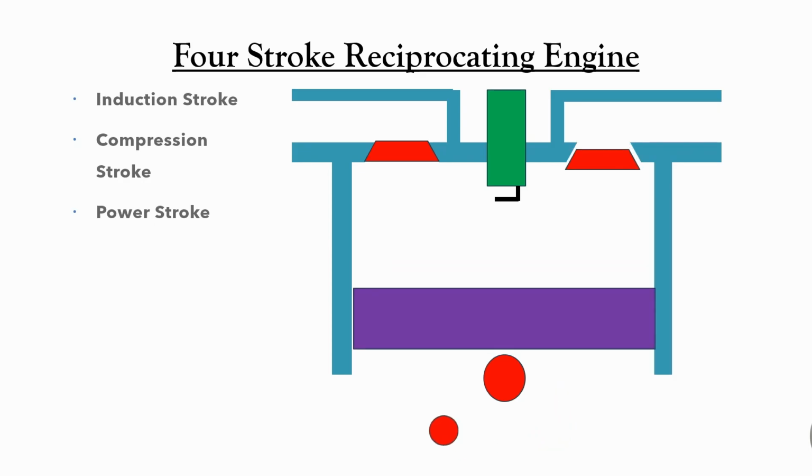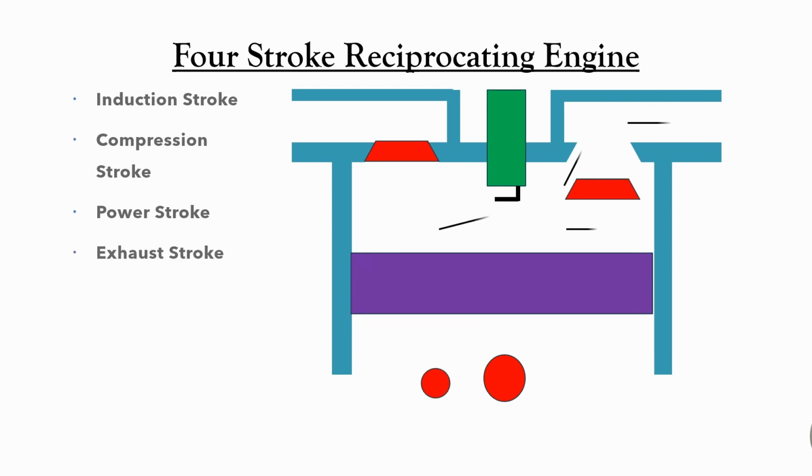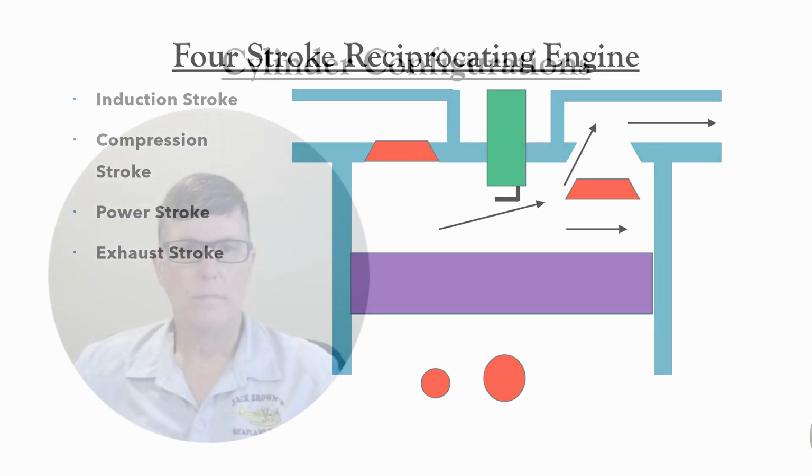During the exhaust stroke, the exhaust valve is opened. The piston moves upward, pushing the burned mixture out into the exhaust manifold. Each cylinder is only producing power for 1/4 of the time. However, most aviation engines have 4 or more cylinders. The strokes of the cylinders are interleaved so that the power is close to continuous.